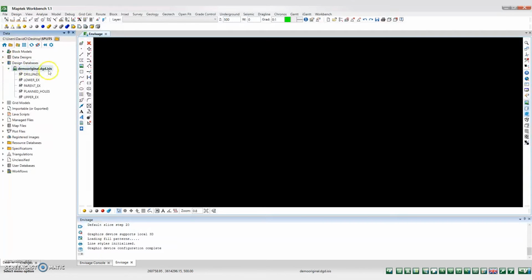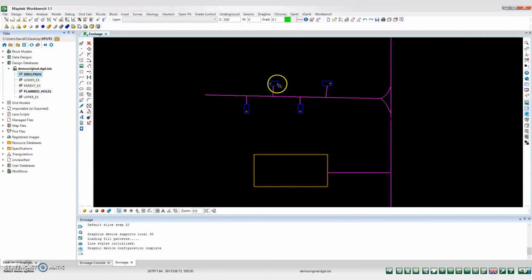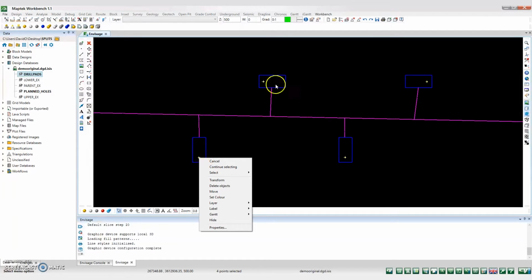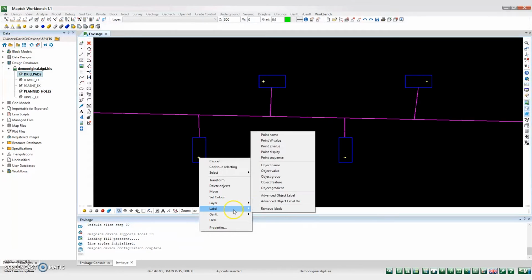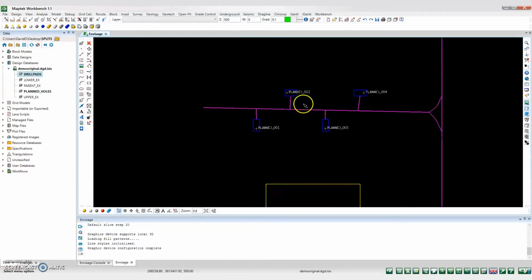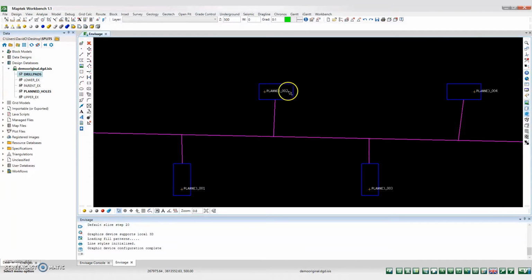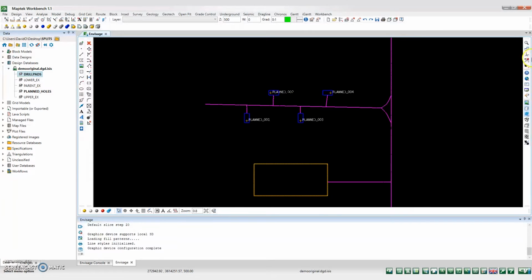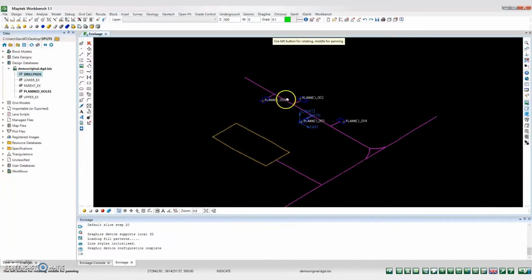So I've made a layer for planned holes. There's just some infrastructure there, so each of these orange dots is going to be a planned drill hole. You can make those however you like, they're just normal design data. Now, one of the attributes that those points have is a point name. So if I label them by point name, you can see that I've given them the planned drill hole name on those points, and I've registered them to the topography. So that's our starting point.